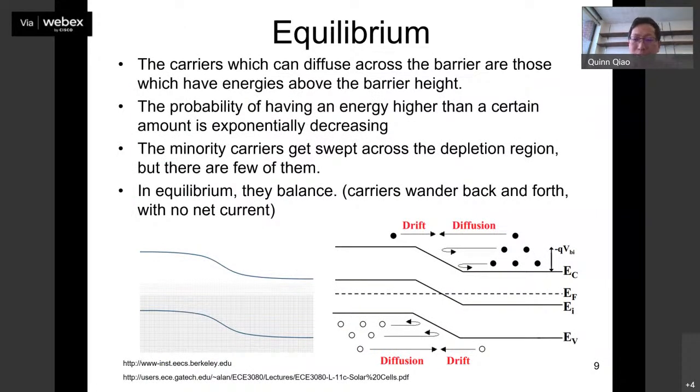What you see here is the Fermi level. This is EF, this is EFN. They are aligned. And then there's EI. EI is called the intrinsic energy level. That's just halfway between EC and EV. That's why EI is bent the same way as EC or EF.